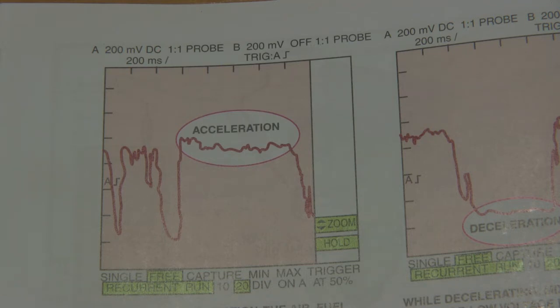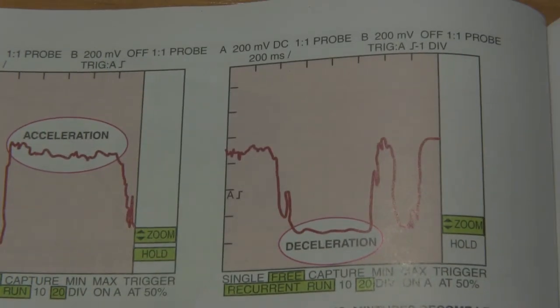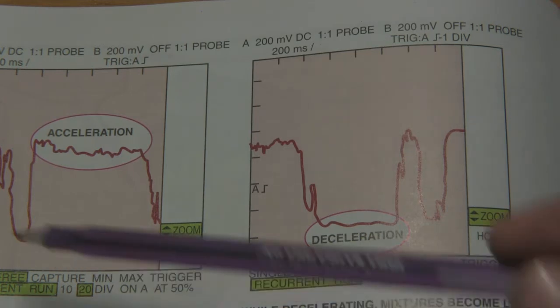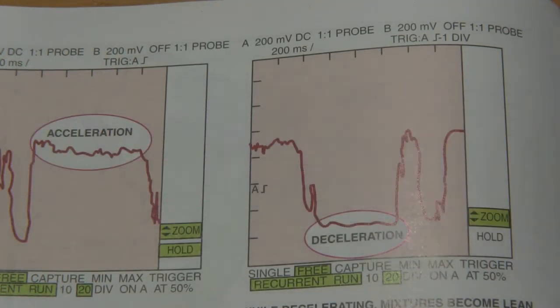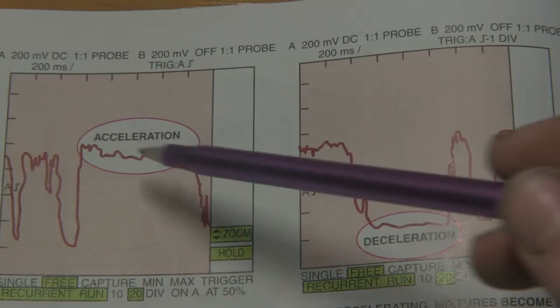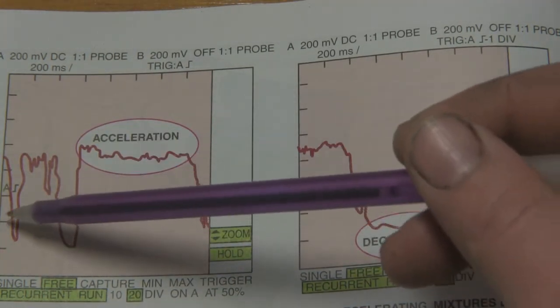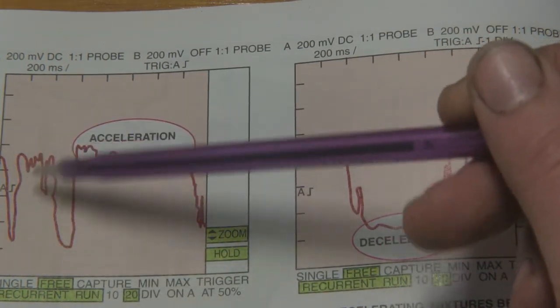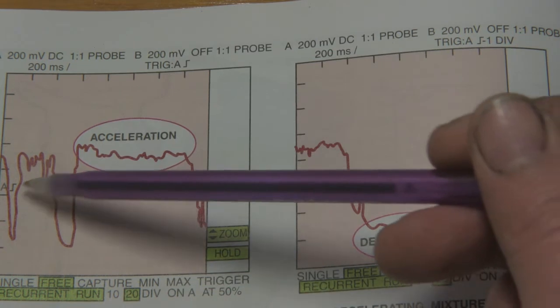And so what happens when we go to full throttle scenarios or zero throttle? We are coming off the interstate and we snap the throttle plate shut. What should the oxygen sensor do in reaction? These two slides are discussing that. So if we look here, we've got this kind of craziness going on. Now, let me move over a little bit. Okay, so we got this little craziness going on, which is normal. This is what I'm talking about, where the scan tool is going to kind of mask some of these weird oscillations that you might think are problems, but they're really not.